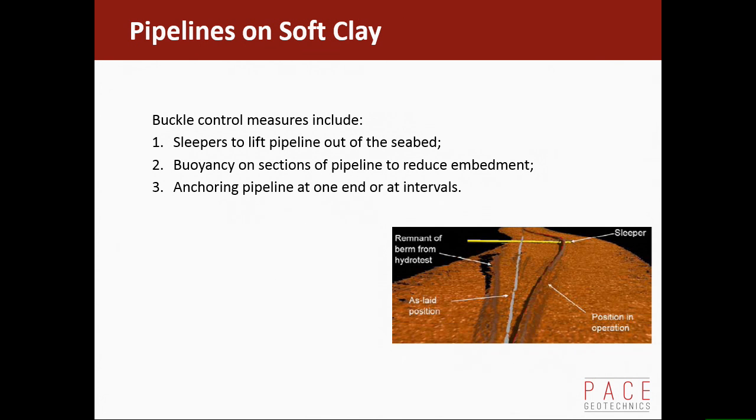Now there are various ways to control buckling of pipelines. One of the ones that is used is to put a sleeper under the pipeline at intervals and effectively snake lay the pipeline. So if you snake lay it, you know, because you know the temperature that you expect in the pipeline.